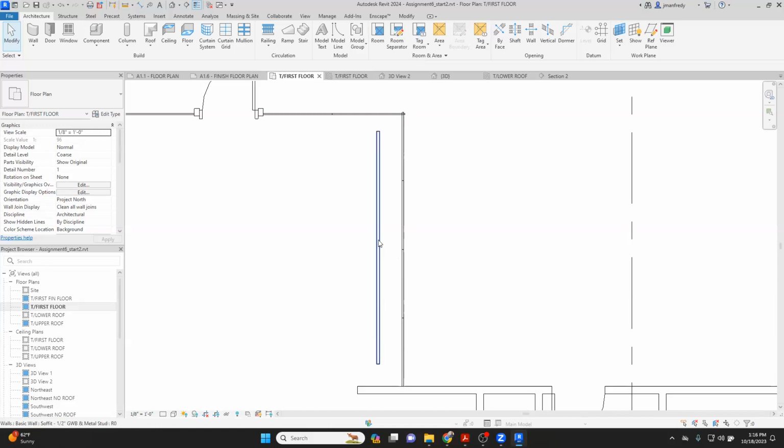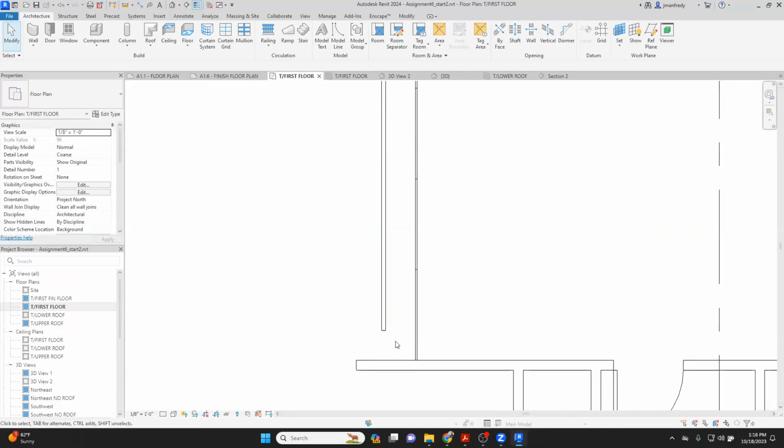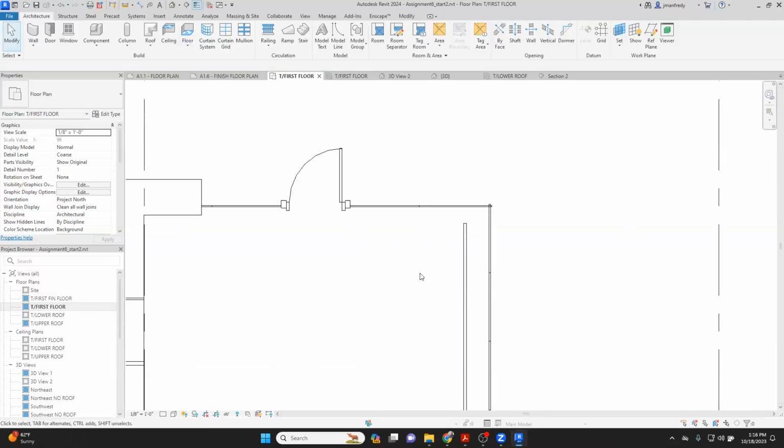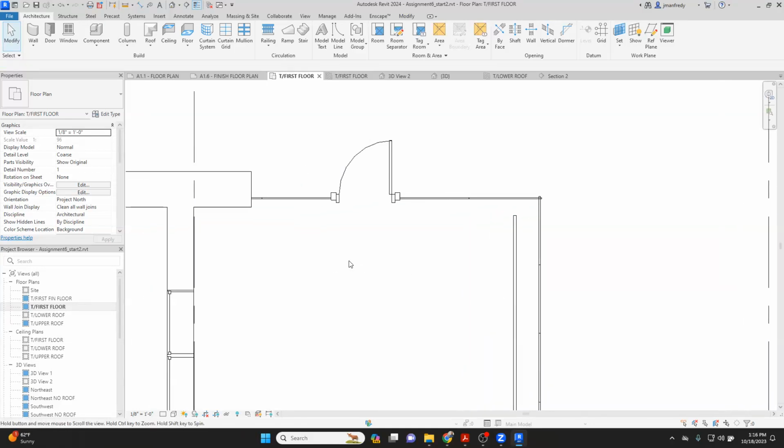Once you see it up there, then you can adjust it to align with the wall above here. I don't know where that beam is supposed to be. Now, I know it's going to connect to this wall, so I'm going to line it up there for sure. I can't see where that beam is. I'd like to see where that beam is because this wall runs into the beam above this room. So I can display that beam, and that's what underlay is for.